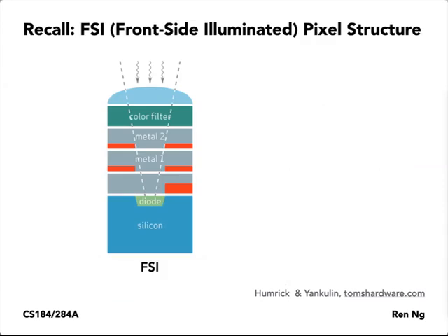And then on top of that are added these metal layers, through a masking and buildup process. That's the way that fabrication happens normally in a CMOS manufacturing process. That's why you end up with this metal effect and the color filter array distanced away from the photodiode. That's called front-side illumination, or the typical manufacturing approach.